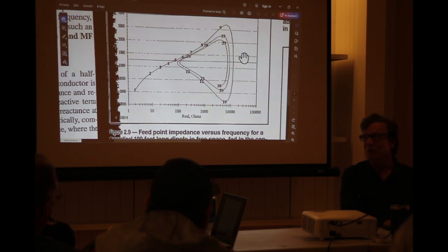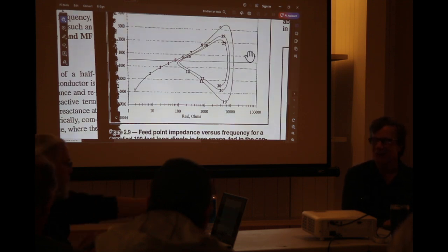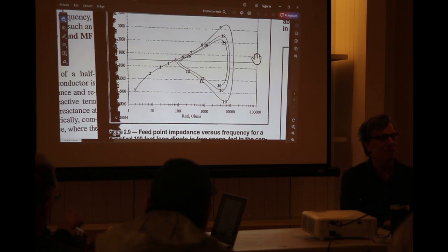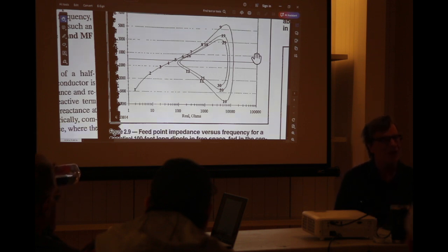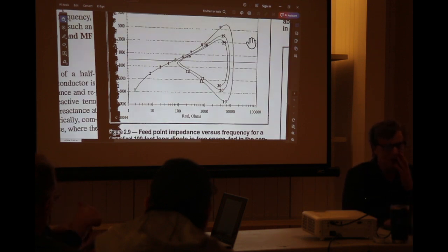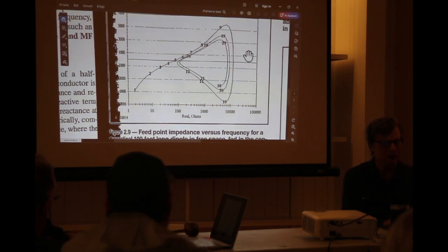But it only does that one frequency. Right. So the ZEP antenna and a J-pole is nothing but a stretched out ZEP antenna. You have the same thing. You have the quarter wave matching section, which is feeding the end of a half-wave vertical antenna. So right off the bat, we see we're going to have some issues here when we're building an end-fed half-wave